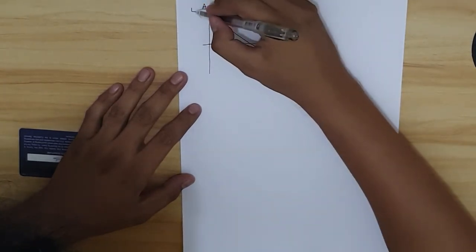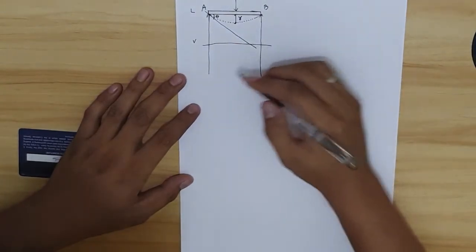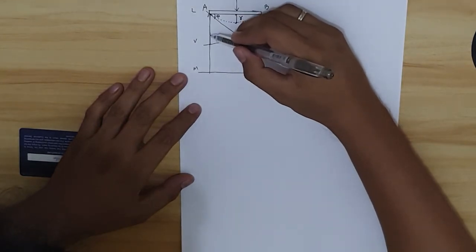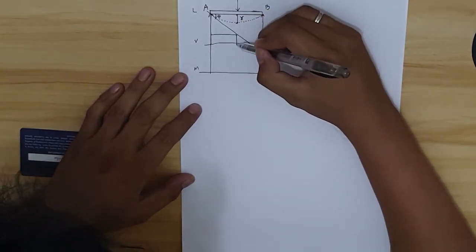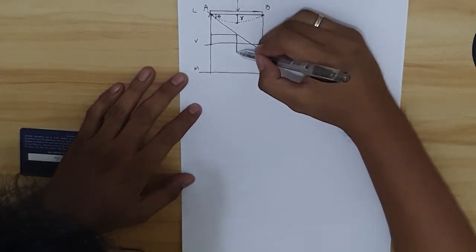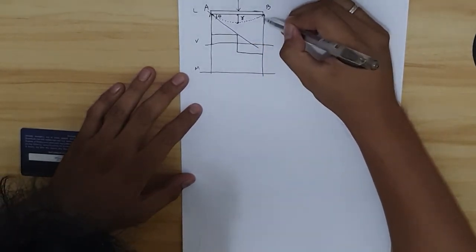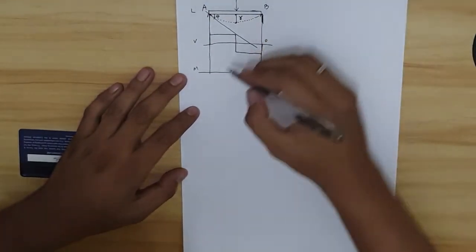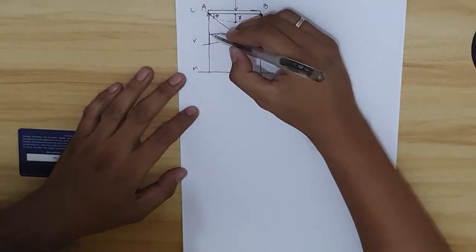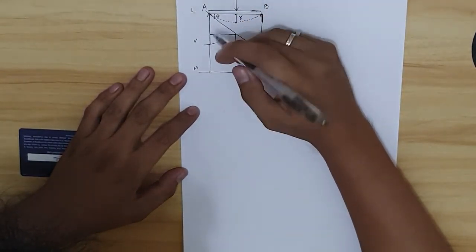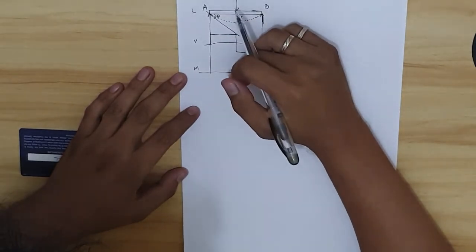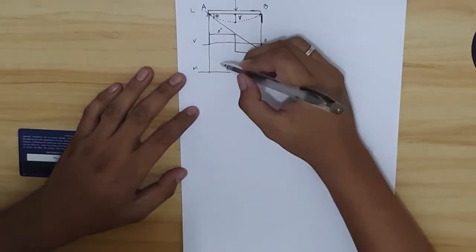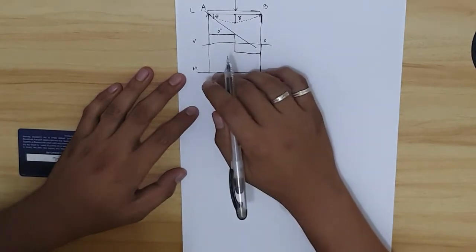This is the load diagram. Then we have the shear, and then the moment. The reaction is upward, and this is downward for the load P. Then there is no load in between, then the reaction, so it goes to zero. If the shear diagram is a straight line, zero degree, automatically the next diagram would be first degree.